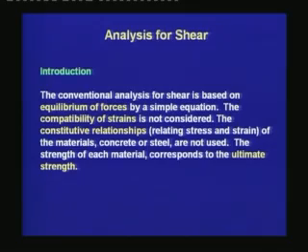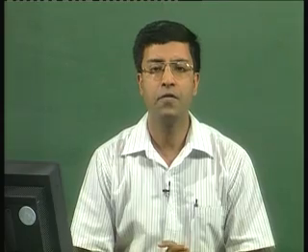The approach that we followed for axial load and flexure was more rational compared to the approach that we shall follow in shear. For shear, we shall consider only the equilibrium of forces. We are not considering the compatibility of strains in the concrete and steel. Neither shall we use the constitutive relationships which relate the complete stress strain curve of each material.